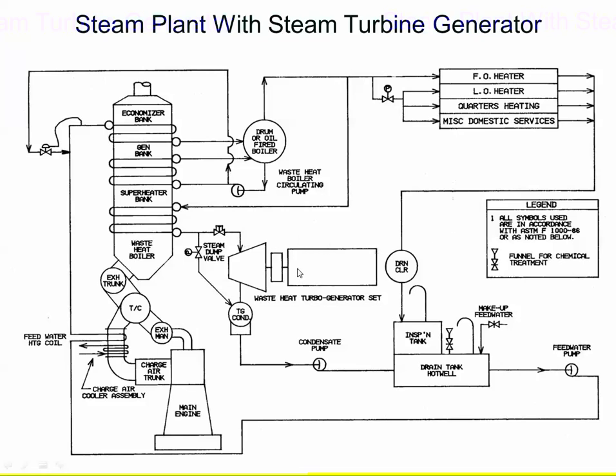So what happens is, if my boiler pressure starts getting high, I will increase the input to the governor to increase the load on the steam turbine, which means that it will demand more steam flow to the turbine, which will drop the pressure, and it will produce more energy. The shaft generator will have to produce less, which means more engine power is going to the prop, and the ship would speed up a little bit. So this is just supplying a portion of it, and I can change the load on this generator to control my boiler pressure.